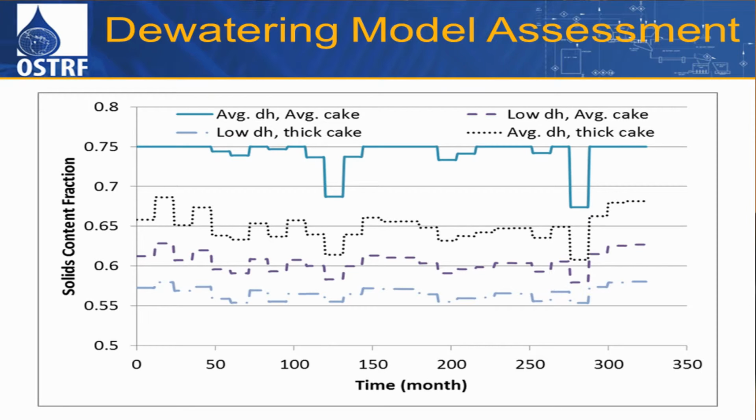There are also variations in the flow rate going into the system. If you have a static system and a static number of pipes, and your flow rate is too low, your velocity is going to be a lot lower, so your cake thickness builds up, and your filtration rate drops. In the worst case scenario, if your filtration rate is too low, that bottom line, you're barely dewatering your tailings, and you're getting segregating product out of the end, and you're forming a beach and having that thin fine tailings running off.